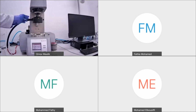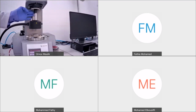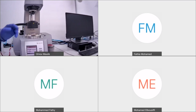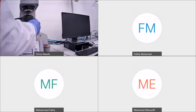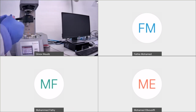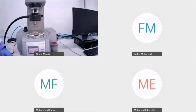You can see now the geometry is fixed to the coupler. Yesterday it was rotating on the sample. Today we will have it oscillate on the sample to determine the viscoelastic behavior of any sample. I'll put some paste sample onto the bottom. You can see I have already placed my sample over here, and then I will lower down the geometry.